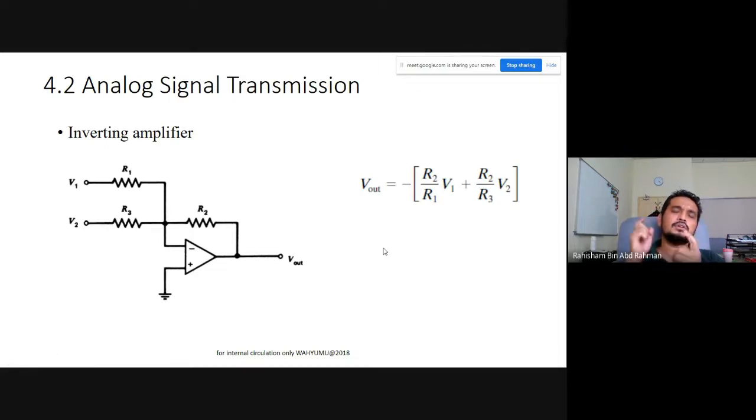Okay, you know your objective is to provide isolation, to amplify the circuit, to what else? To perform a low pass filter. So you need to add 3 circuits: voltage follower, amplifier, and low pass filter.